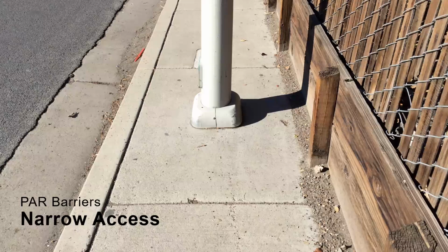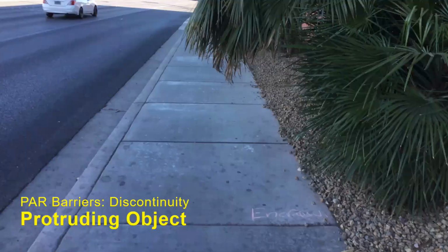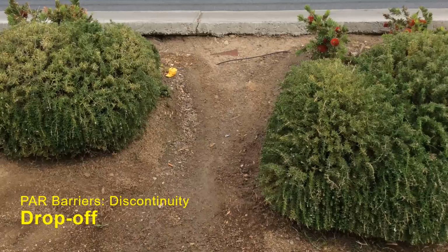Narrow access points, less than 48 inches, may be easily navigated for ambulatory pedestrians, but for someone using a powered wheelchair, this utility pole denies access and puts the pedestrian at risk of injury or death if they try to maneuver around that pole. Protruding objects, which protrude into areas which are not detectable by people with vision impairment or who are simply distracted, can be a potential hazard. Drop-offs greater than 6 inches, though not specified in accessibility standards, can present a potential danger to both ambulatory and non-ambulatory pedestrians if they veer too far off the side of the sidewalk.